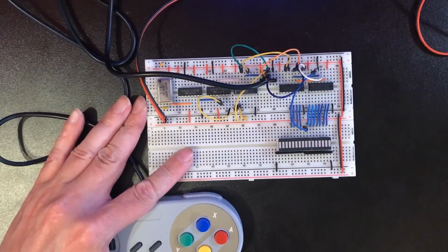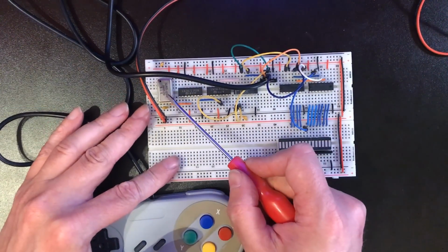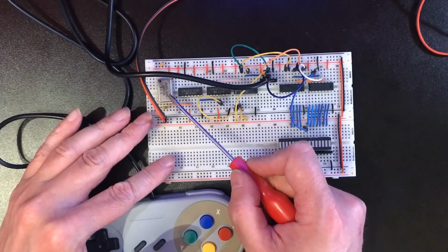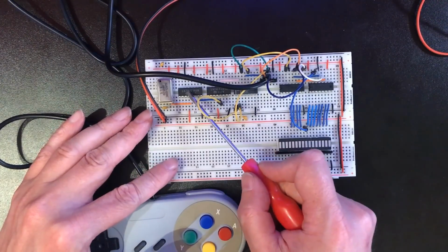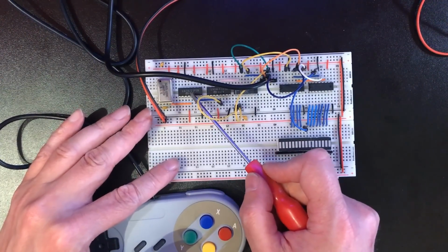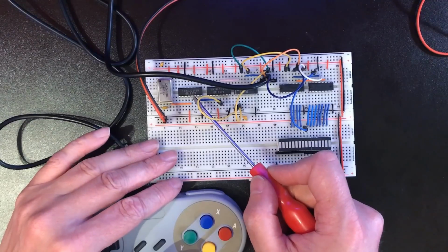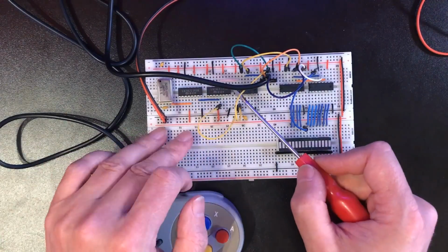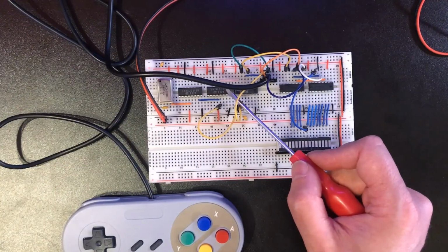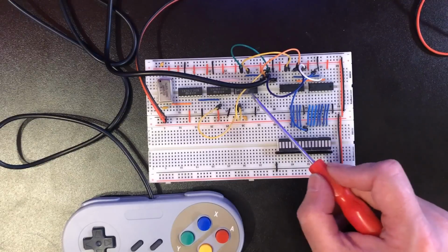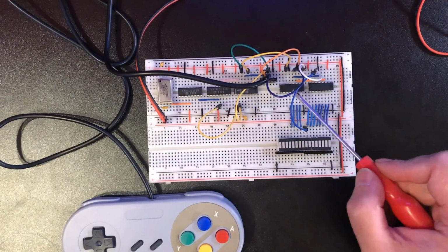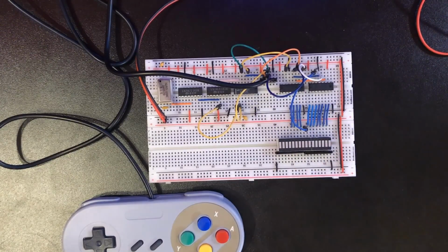So here's the circuit we built last time. We got the clock input, which we're expecting the crystal to be on another circuit board, but we divide that down by 16 using a counter just to make the overall frequency a little bit more reasonable. We have a counter to generate the latch signal every 16 ticks. We've got an inverter we use for a number of things, and then we've got the shift and latch registers.